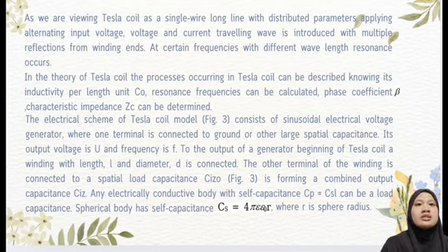The electrical properties in Tesla coils are spread out, or distributed, across the entire coil. These properties include 2 elements, which are inductance and capacitance. The inductance is able to store energy in a magnetic field, while the capacitance is able to store electric energy between turns of the wire and against the surrounding air. This value depends on the coil wire and design. More turns means higher inductance, while tighter spacing between turns means higher capacitance.